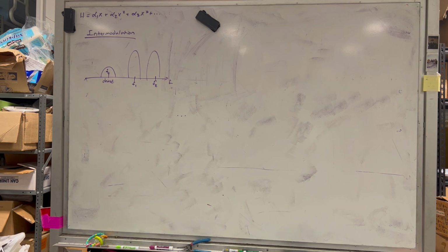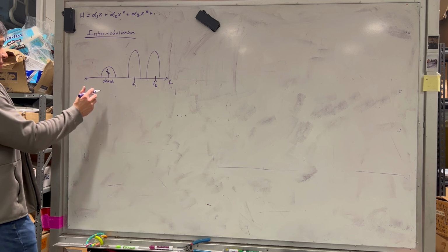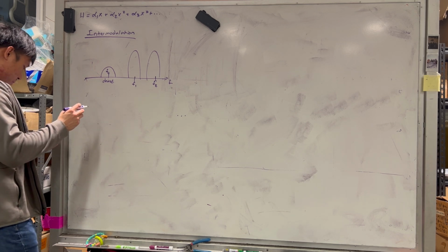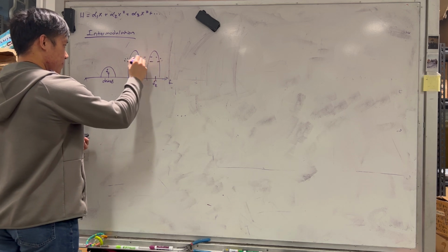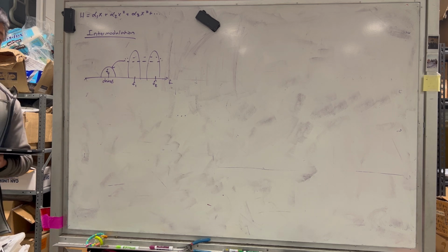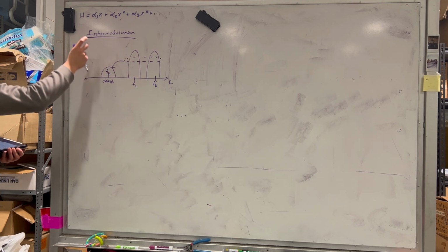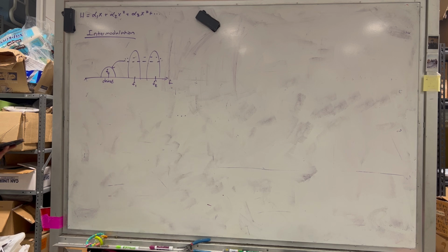Right? If you remember from the mixers lecture, do you guys remember the third order harmonics that you see, what frequencies they are? Assuming you do, here you see some of this essentially pop into there, right? Because you get like 2F1 minus F2, and then 2F2 minus F1, blah, blah, blah. You get all of that kind of dumped onto the desired signal of interest, right?